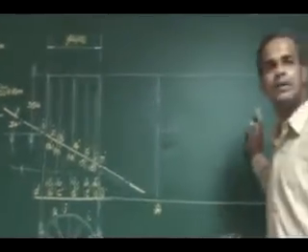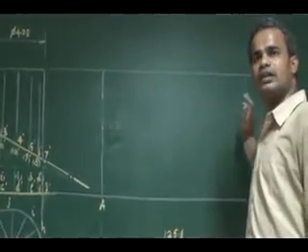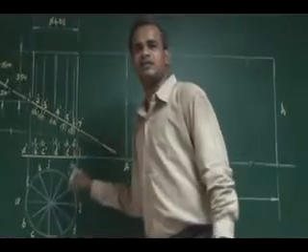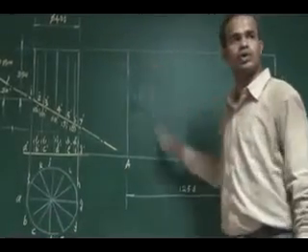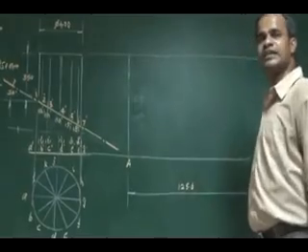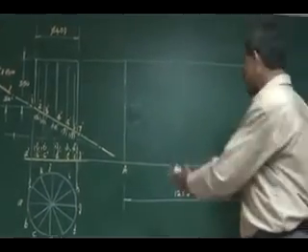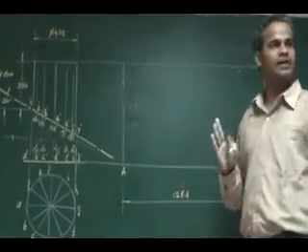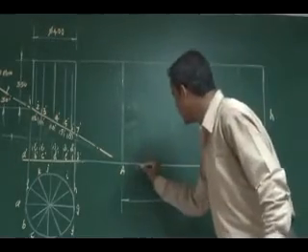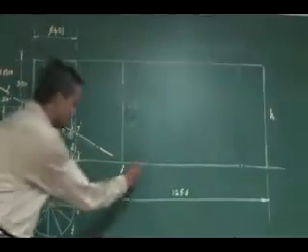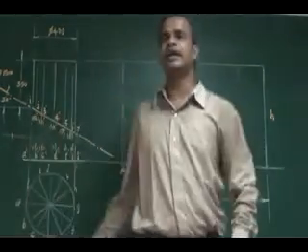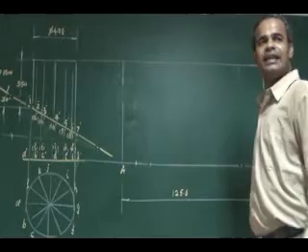Now this development is a rectangular sheet for a cylinder. So I have 12 generators here. These 12 generators have to be shown in your development first of all. How can I do that? This 125.6, either using construction procedure you can divide it into 12 segments, or you divide 125.6 by 12. So what is the value you are getting? That division is 10.4, I can cut it. So you can measure 10.4 and you can get 12 divisions.